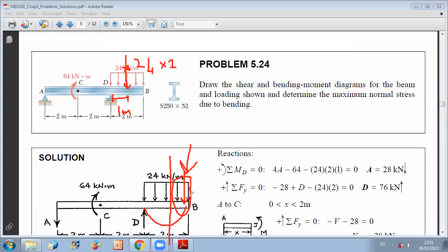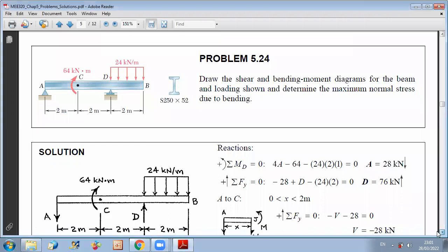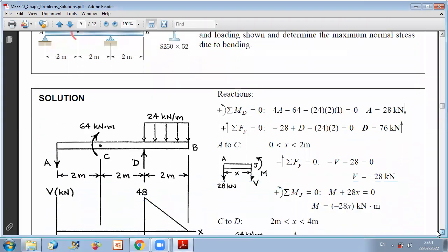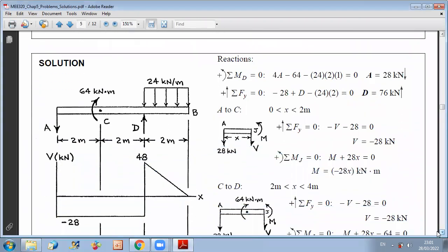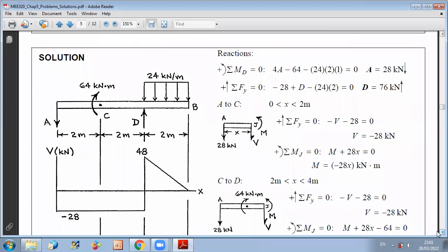And when we do the cut, internal forces become external reactions. Then we can replace the distributed load on the remaining part by a concentrated force. Now, let us use the area method or the section method. So here, again, you can practice with this problem with both methods of section and area.